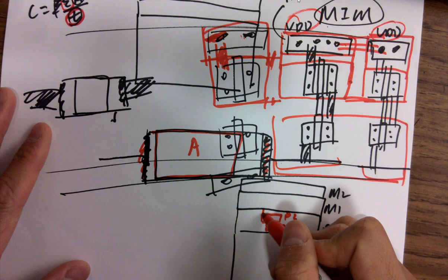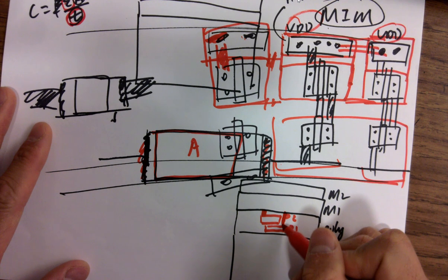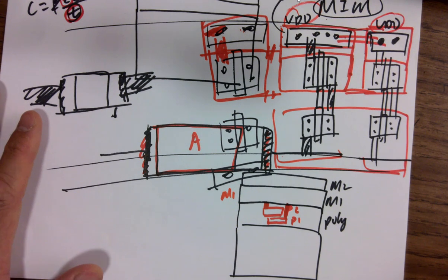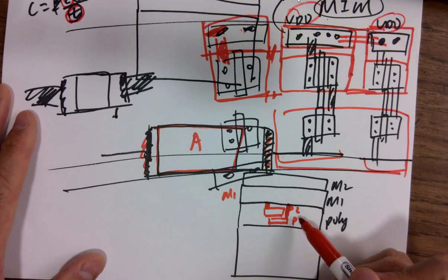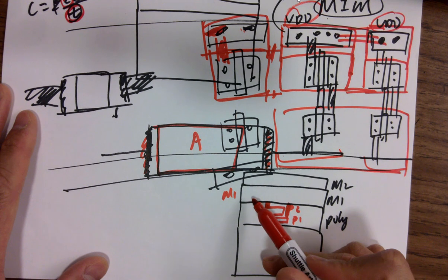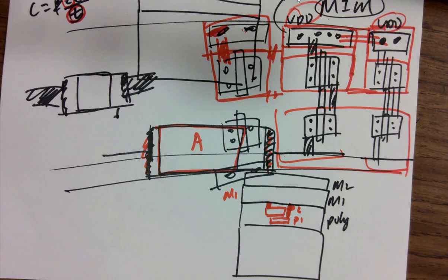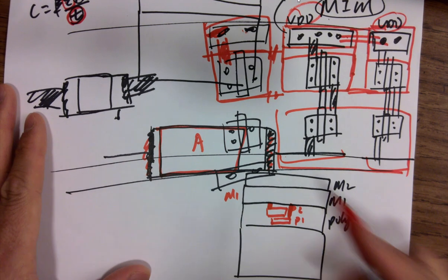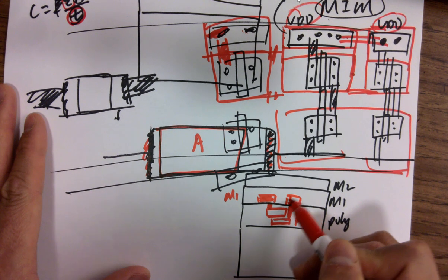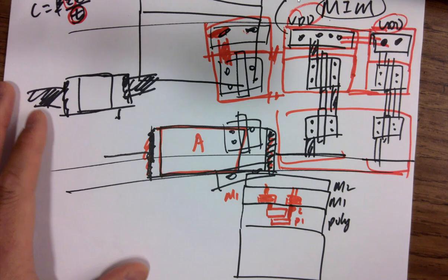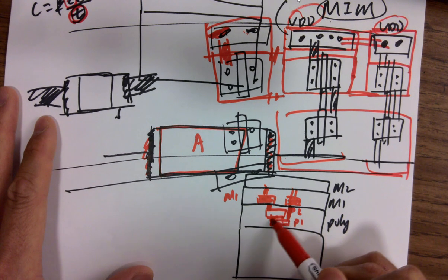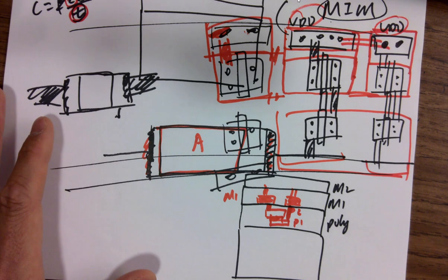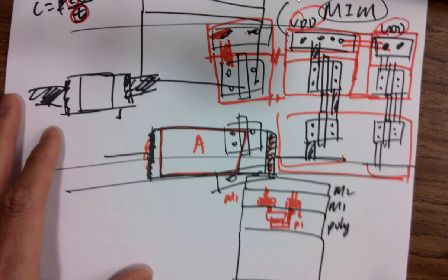So for the vias and connectors for P2 and P1, it should be both metal 1s. So it should be poly to metal 1 vias, but there are different vias. Poly 1 to metal 1 via will be different from poly 2 to metal 1 via. Obviously, right? There are different poly layers, so there are different vias. And they have a metal here, and they can connect to metal 2, metal 3, eventually connecting to all the circuits. So this overlapped area will form a capacitor, using that very thin dielectric material, silicon dioxide, in the middle.